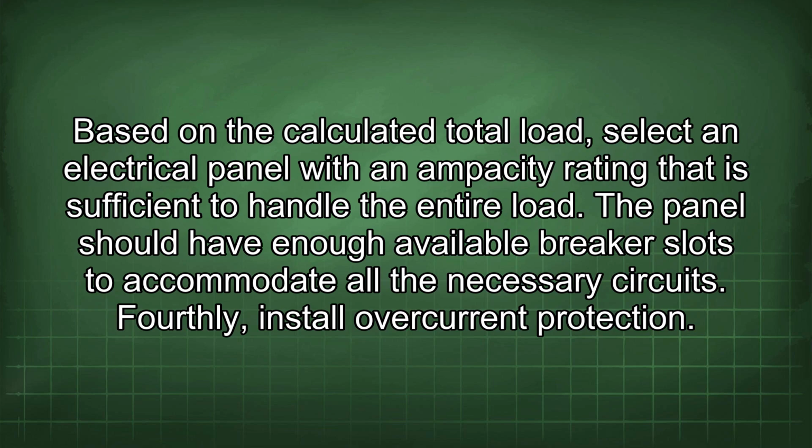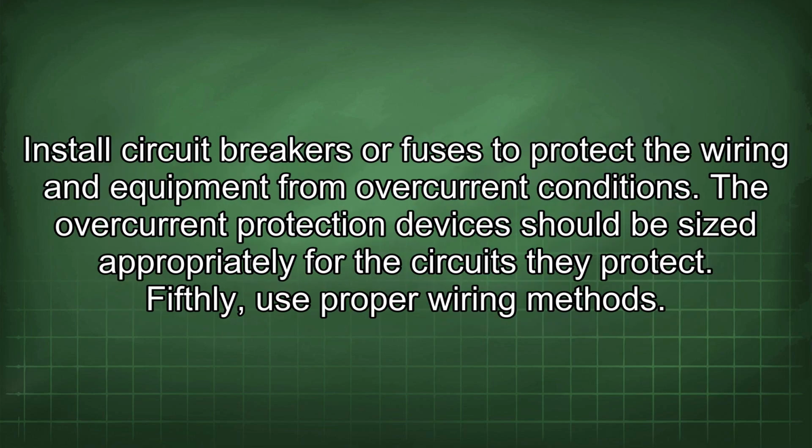Fourthly, install overcurrent protection. Install circuit breakers or fuses to protect the wiring and equipment from overcurrent conditions. The overcurrent protection devices should be sized appropriately for the circuits they protect.